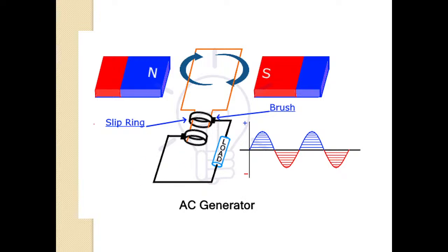It is used to transfer DC power to the rotating field windings from a DC battery using brushes. The brushes will be sliding on the slip rings, and they will collect the current from the slip rings and give it to the load.